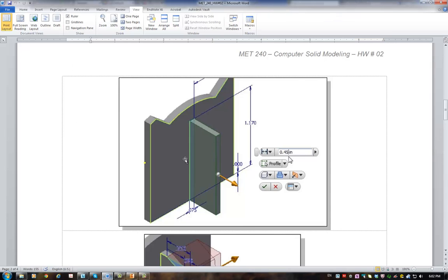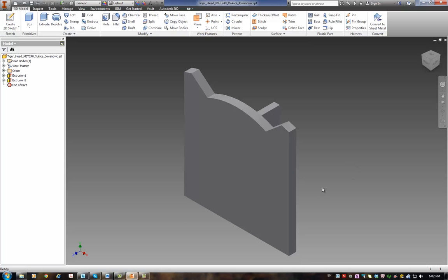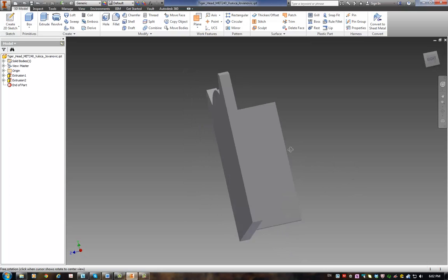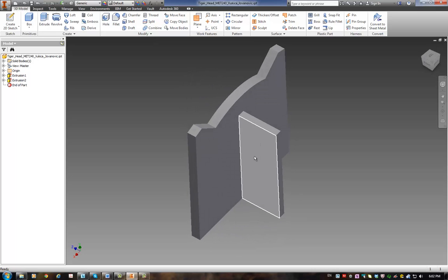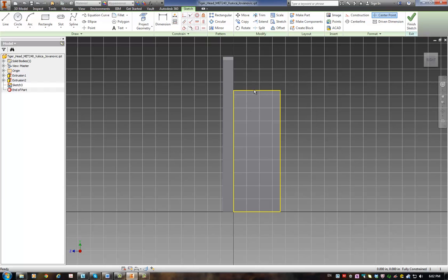And now I will do this thing at the back. So you see there's 1 line, 2nd line, 3rd line, 4th line, and then the cut through this kind of region. So for that I'll use again Control and turn this around, and I will select this as my sketching plane. So I will go to Create 2-dimensional sketch, click here. And for this, I can use the existing geometry here that I have. You see this yellow. So I can say line, and I can click somewhere here, and just go down.